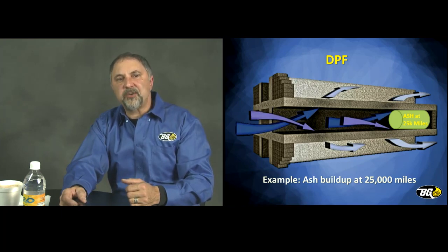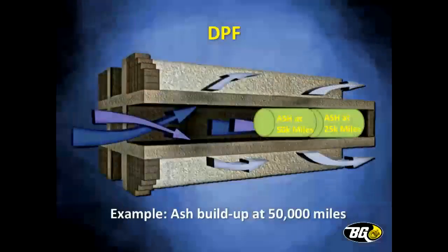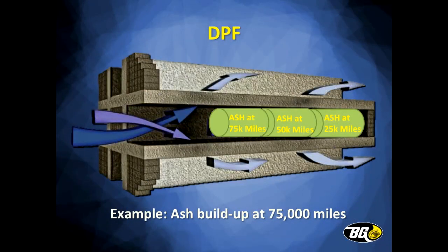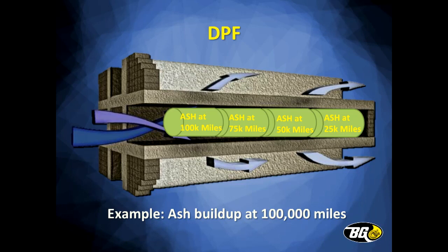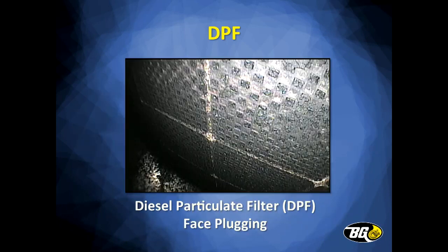Soot burns off, ash remains. Then we're getting to 50,000 miles, it's burning 3 times a week. Then 4 times a week, now it's regenning every day, sometimes twice a day, before this truck goes into regen, goes into derate and you ain't moving it anymore.